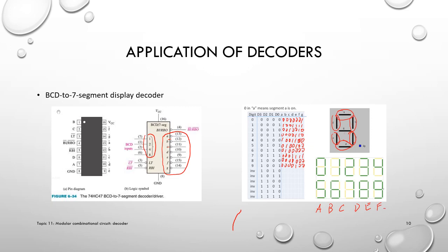However, because if we display a big B, it will be the same as 8, we use a small b instead. Similarly, a big D would be the same as 0, so we use a small d. Okay, then let's see what will happen.